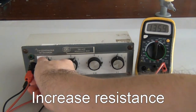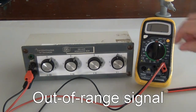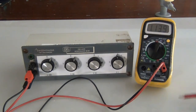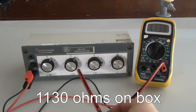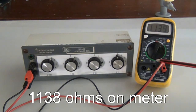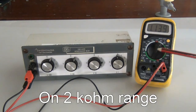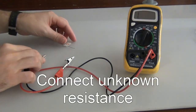We increase more resistance and we see that we have an out of range signal, so we have to select another option. Now we have 1130 ohms and it reads 1138 ohms on the 2 kilo ohm range. So the 2 kilo ohm range means it reads a maximum of 2000 ohms.